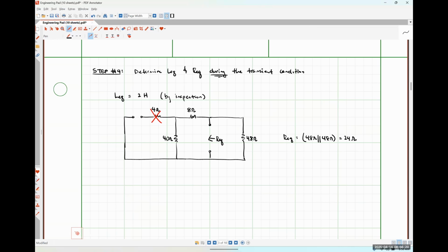We're always finding the Thevenin equivalent, which means we need to be looking at a dead network representation. When we find the resistance, we're looking from the terminals left behind by taking the energy storage element out. If we had multiple energy storage elements, we would find the equivalent energy storage element by taking the equivalent resistance out and looking at it. Carter, what was your question?